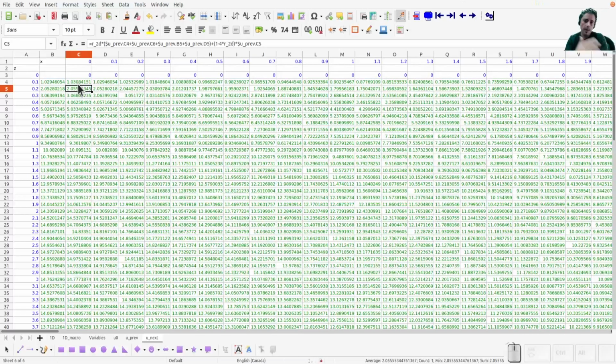So this type of calculation using the explicit finite difference is very good for parallel processing. Matrix inversions, so if you want to solve finite element or the implicit method or Crank-Nicolson method in finite difference, you have to solve the matrix, which is less good because things are interrelated.